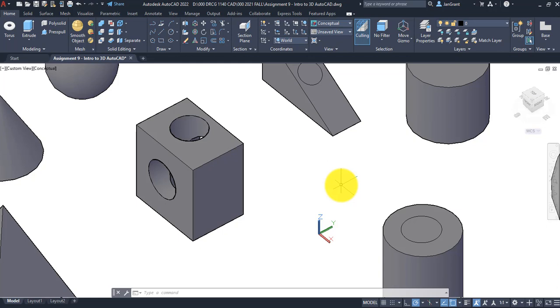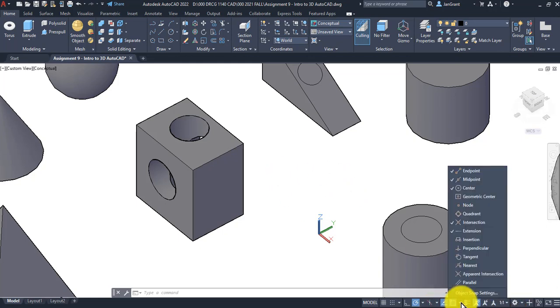And we're going to develop something in this exact file that is more of a 2D turned into a 3D. So if you wanted to draw the circle on something else and subtract it, that's okay too. All right, let's make sure that the object snap midpoint is on, so we could draw a line from midpoint to midpoint. So here at the bottom right, click on the arrow next to Object Snap and just make sure the midpoint is checked. Mine is, so I'm good.